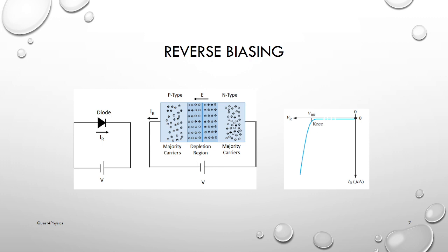And as we can see, in the voltage-current characteristic in this case, at zero bias condition, the reverse current is strongly vanished. If the reverse bias voltage is increased, a very small reverse current is seen. The reverse current increases rapidly only when the applied voltage exceeds a certain value, which is called the breakdown voltage.